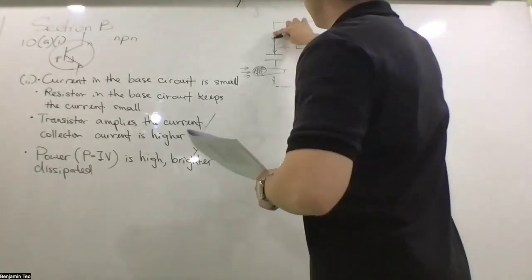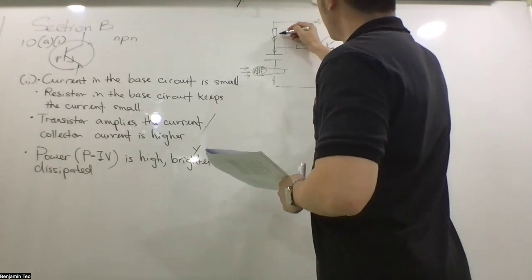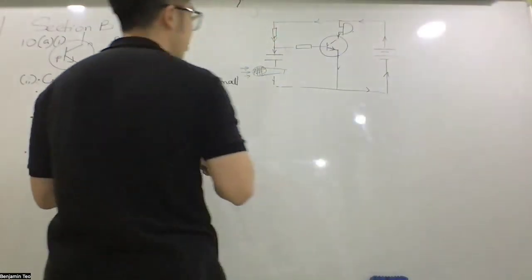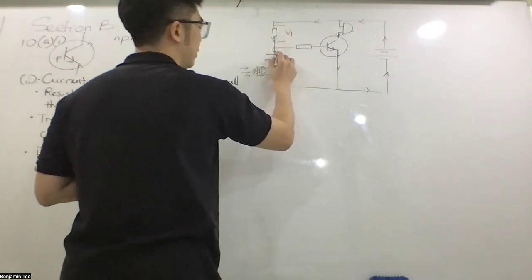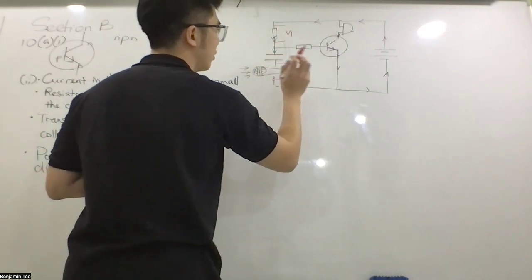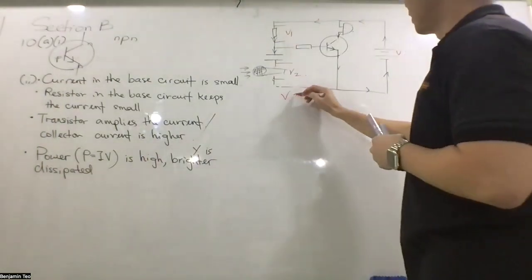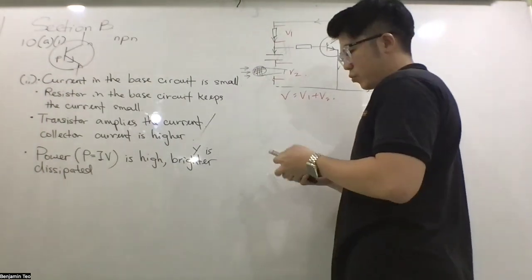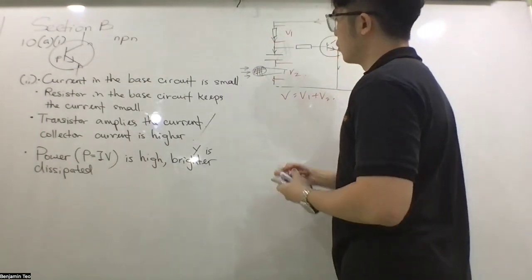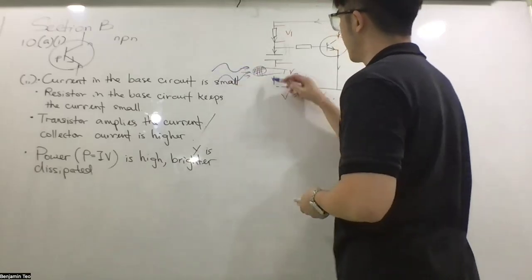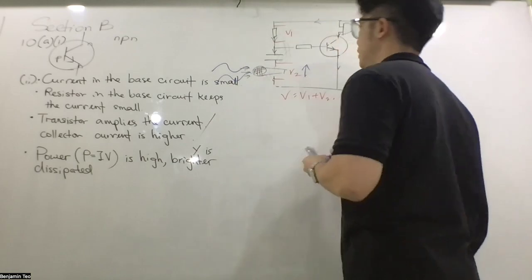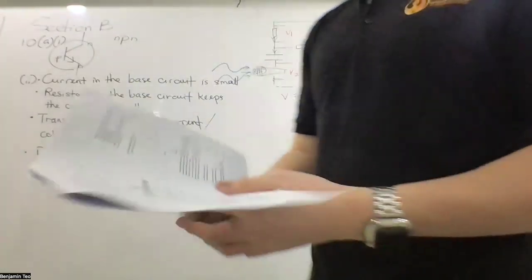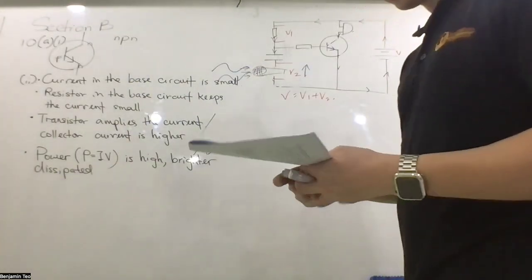And then the P, we're going to put a fixed resistor here. What is it for? It's basically just to create a potential divider. Because you know the voltage here, this is V1, and the voltage here V2, is equal to the total voltage V equals V1 plus V2. Okay. So how it works is that when the baby cries, you pick up sound. So a current is generated, voltage will be higher. That will turn on the transistor and sound the alarm. Okay, so that is our design.